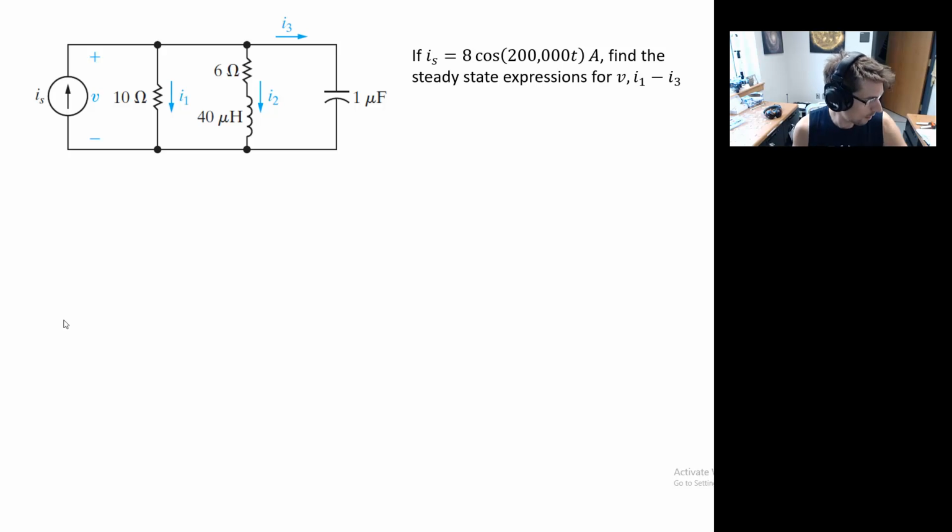Okay. Alrighty then. Let's get at this sucker. So the first thing I'm going to do is, rather than treating it as a cosine of time, transfer into what's called the frequency domain. That's where we use Euler's relation in order to introduce that imaginary component. And then we can think of this source as simply being the projection of a unit circle onto the real axis. So we can take this oscillatory source and start thinking about it as a rotation.